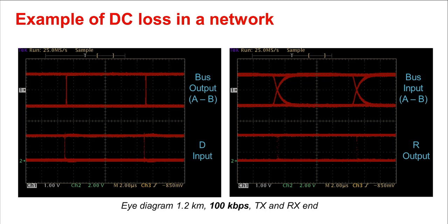On the left-hand side, the output can be observed, which seems to show an almost instantaneous rising and falling edge, while the receiver sees rising and falling edges which look like RC constants due to the cable parasitics. The output denoted as R can be seen transitioning at almost the same time each bit flip, and the jitter present on the cable receiver looks to be minimum compared to the bit width.